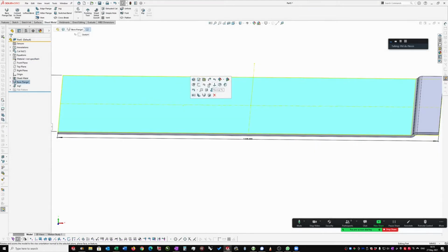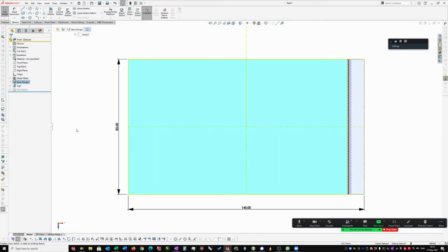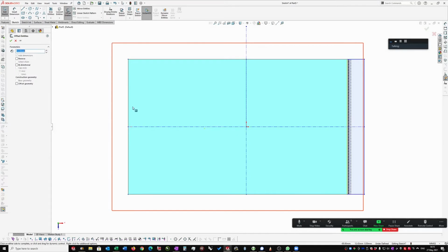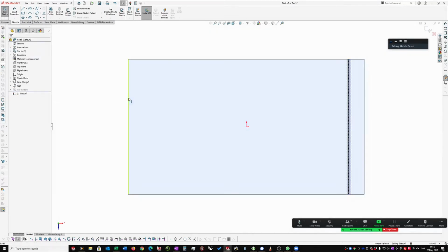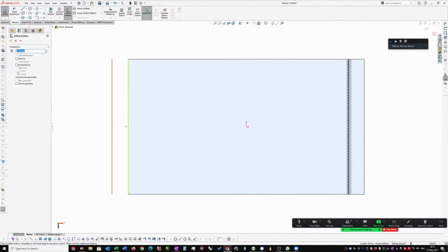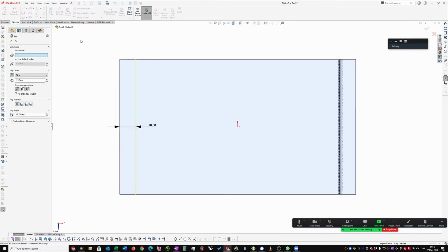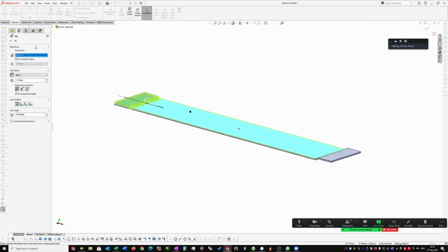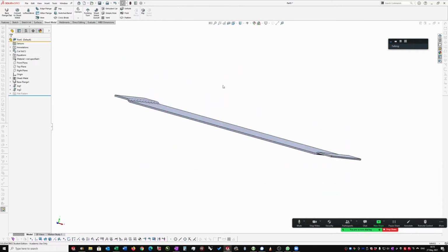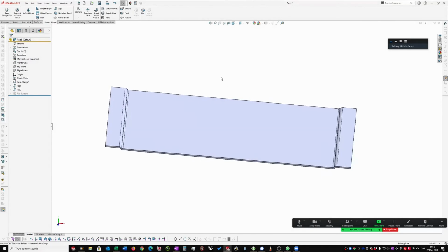Let's put another line in. Sketch. Don't want the whole thing, just want that line. Okay, so straight away it's gone to jog. It says which face do you want fixed? I want that one fixed. And there we go, we've got a jog.